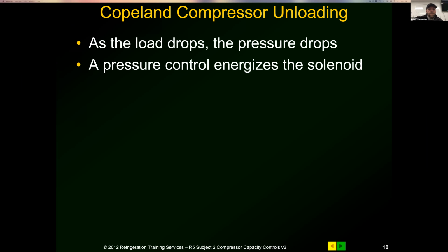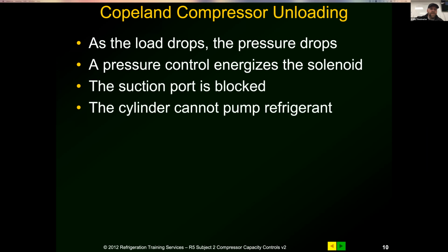No worries. Thank you. So, Copeland compressors unloading. As the load drops and the pressure drops, the pressure control energizes the solenoid. The suction port is blocked. The cylinder cannot pump refrigerant. The cylinder is unloaded.